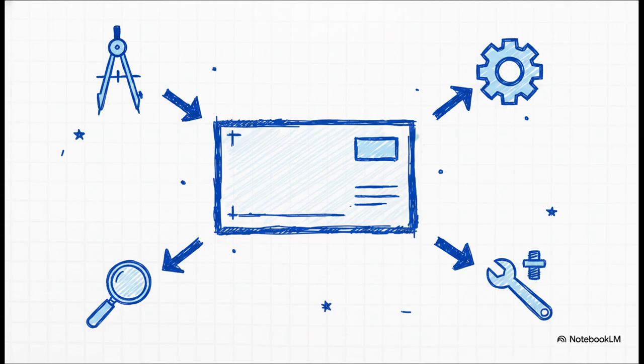The designer uses it to set those ideal functional limits to make sure the part works. But then, manufacturing gets that same piece of paper, or file, and they have to interpret those exact same tolerances to figure out their machining setup, their fixture planning, and their tooling. Then quality and inspection step in, they use it to confirm the standards are met. And finally, assembly relies on it to ensure physical fit. So what does this mean? It means the language of GD&T has to explicitly guide how design intent flows straight into physical production. If there is any ambiguity, the whole system just breaks down.